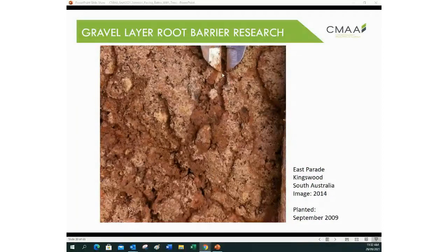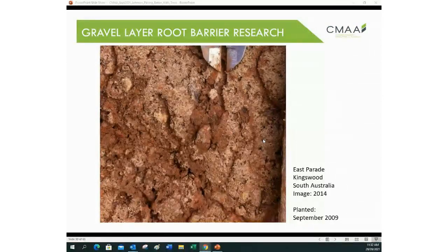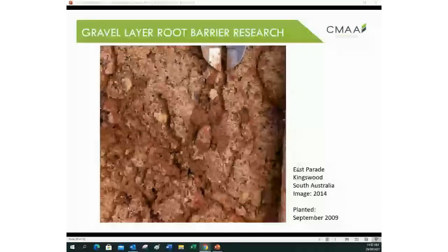These roots here, the largest one in the caliper jaw there, is 2 millimetres. You can see some are deeply incised. You can see a track through here. It's discoloration, but there's no relief. There's no impression into the soil. As it's rained over the seasons, the water's come through the gravel and washed the soil that was imprinted onto the geotextile back into the slot. Just fine root turnover, just restoring the subgrade how it was.